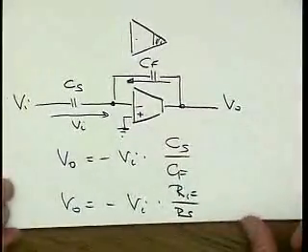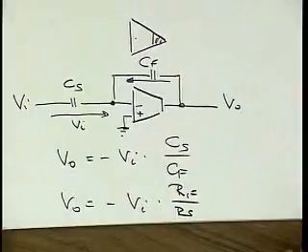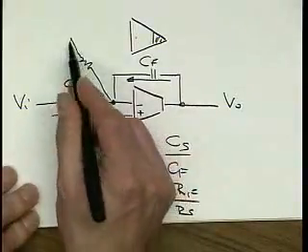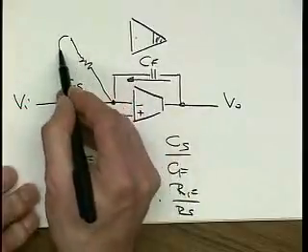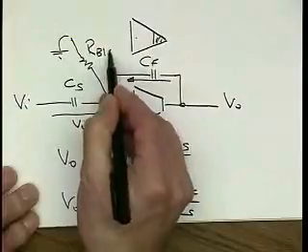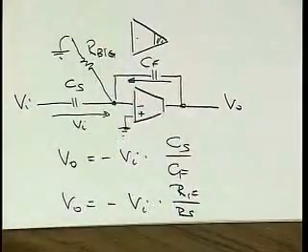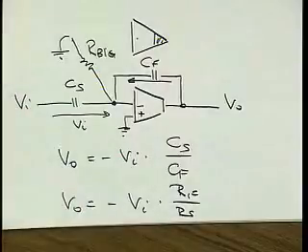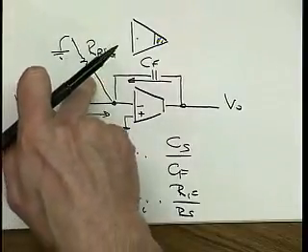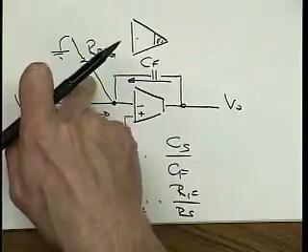There are lots of schemes that come to mind. For example, like we've done in the homework, we could put a humongous resistor, let's say, to ground here or to some other appropriate bias. But in practice, that has several problems. One, the obvious one: how are you going to build this humongous resistor? That would take the entire chip in terms of area.